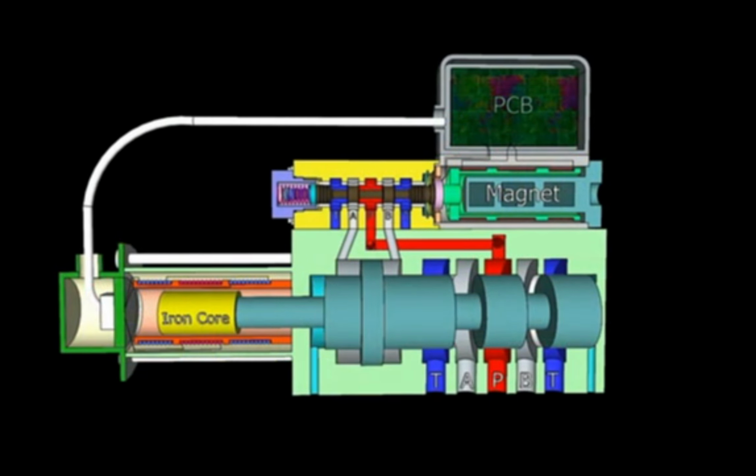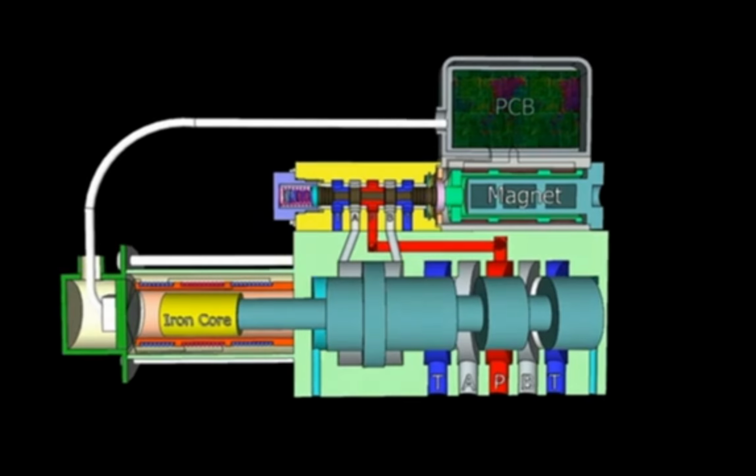And this is the actual setup. The pilot valve is fitted on the main spool valve, and at the end of the main spool valve you can see that an LVDT sensor is there for finding the actual position of the spool, and it is the feedback. It is passed again to the LFE valve PCB, which will compare, and if any error is there, then it will cut off the unit.